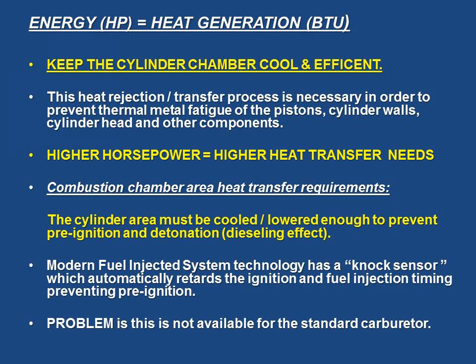Furthermore, the center cylinders normally are going to be running hotter than the front or rear outside cylinder areas. So if we can increase the chemistry and coolant system efficiency, it helps all the cylinders, no matter where they're at, have a much greater even playing field to perform. Again, higher horsepower equals higher heat transfer needs.